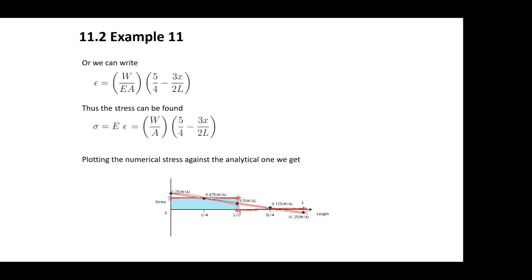It's going to try and minimize the difference. So basically, what the finite element is going to do is try to find the minimum distance of all these points from the line. So it's going to find what we call in math the best fit for this. Now, the best fit is not good enough because you're trying to use a line to interpolate a step function. So it's not going to work. This is what we discussed last week, and I came back to this point because I think it's quite important. And this is what I have been hinting at from the start of the lecture today.